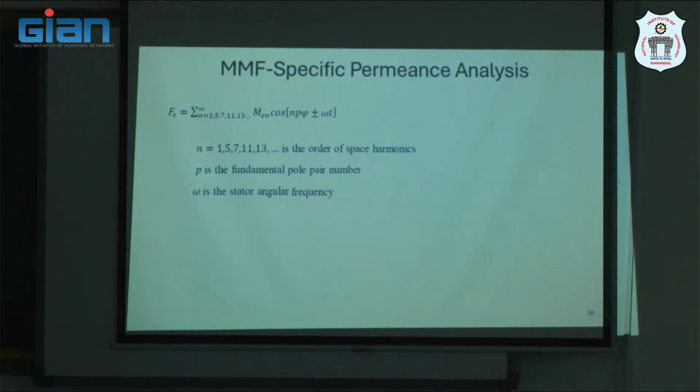Some of you have not. So basically, due to the spatial distribution of the three-phase windings, the waveform will not be exactly sinusoidal. So instead of having a wave like this, we may have a wave like this. Okay. Step or staircase wave. And this staircase comes because we have to place only a fixed number of conductors in different slots.